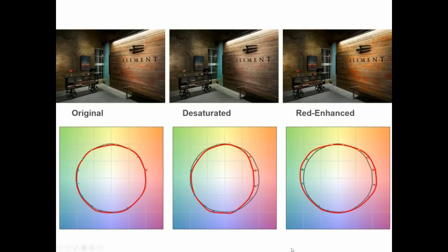So again, my point being here is that we can use these 3 components, the fidelity index, the gamut index, and the color vector or distortion graphic together in order to have a good understanding of what's happening with light source color rendition for a particular spectral power distribution. Now, we hope that people will consider the fidelity index, the gamut index, and the color distortion graphics in tandem, as I just talked about. However, some people might be primarily interested in something that's an improved version of the CIE color rendering index. And that's how the IES fidelity index has been conceived.